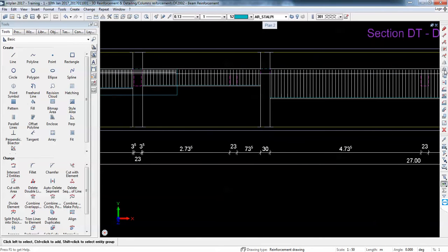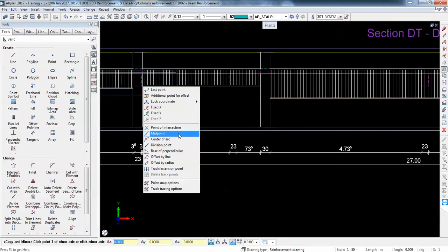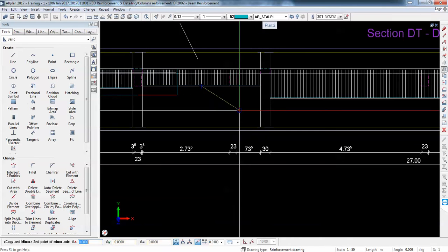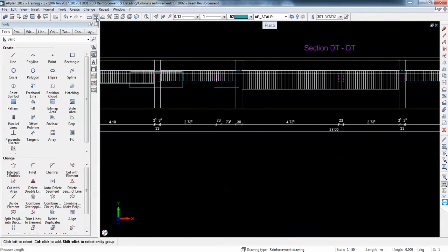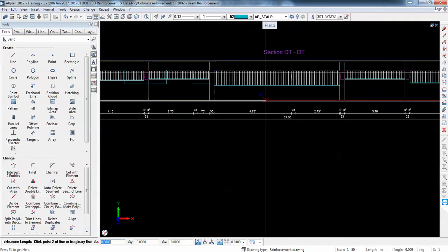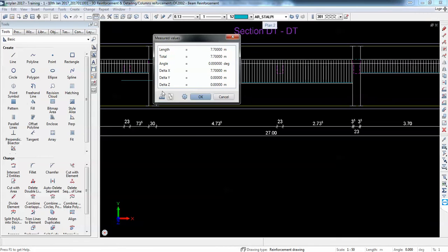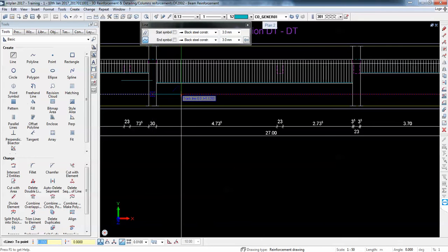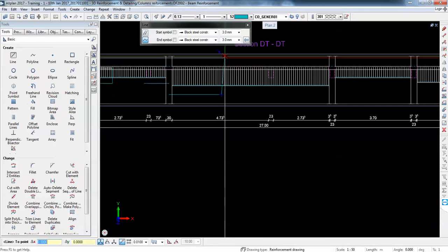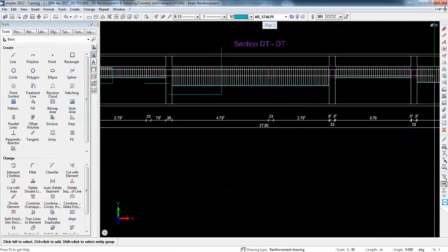So for here we have the same spacing. So I hit midpoint, and in this situation we have a larger spacing, so it will be measured, copy the measurement, hit line, and here paste and divide by 3. So this is where I have to end with the bars.